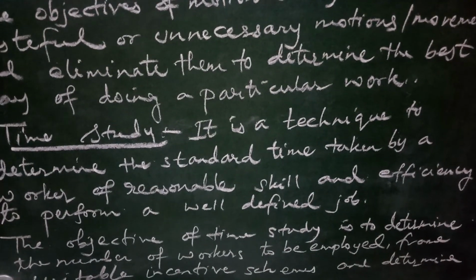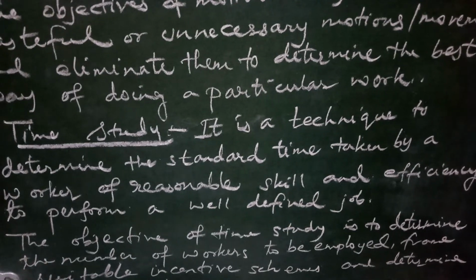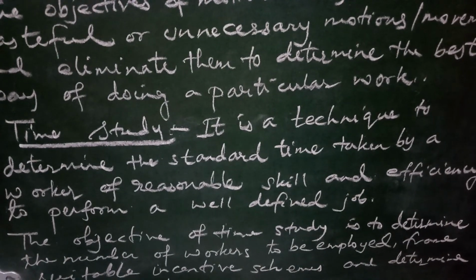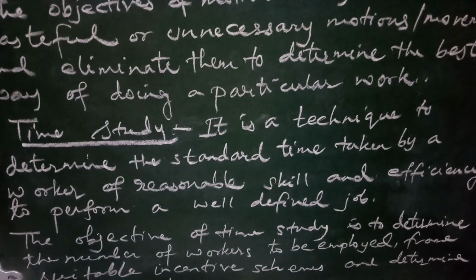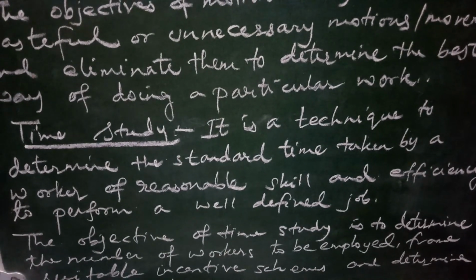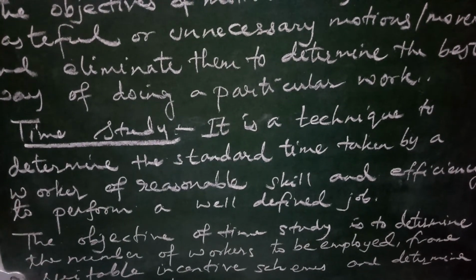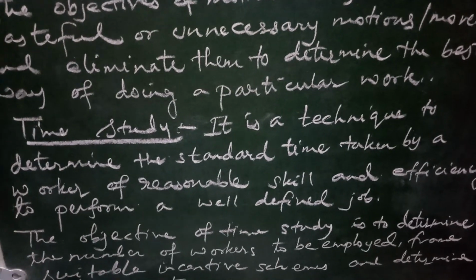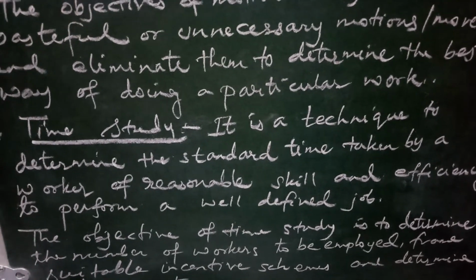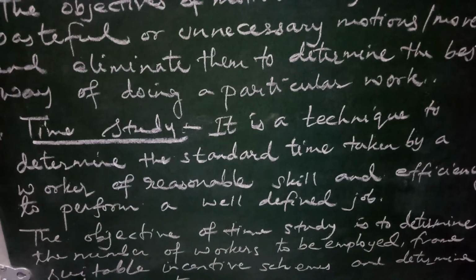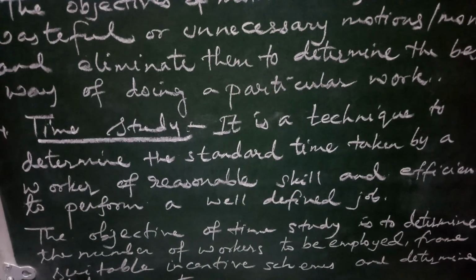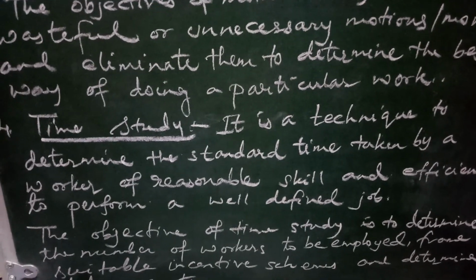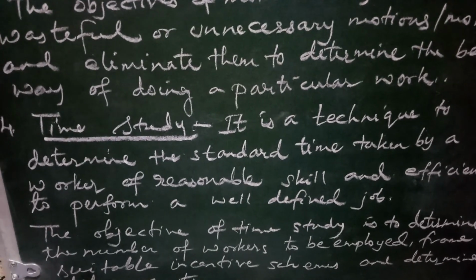Under time study, the job is divided into a series of elements, and the time taken to perform each element of work is recorded with time measuring devices like stopwatches. The standard time is fixed for the whole of the task by taking several readings. The method of time study depends on volume and frequency of the task, the cycle time of the operations, and the time measurement cost.